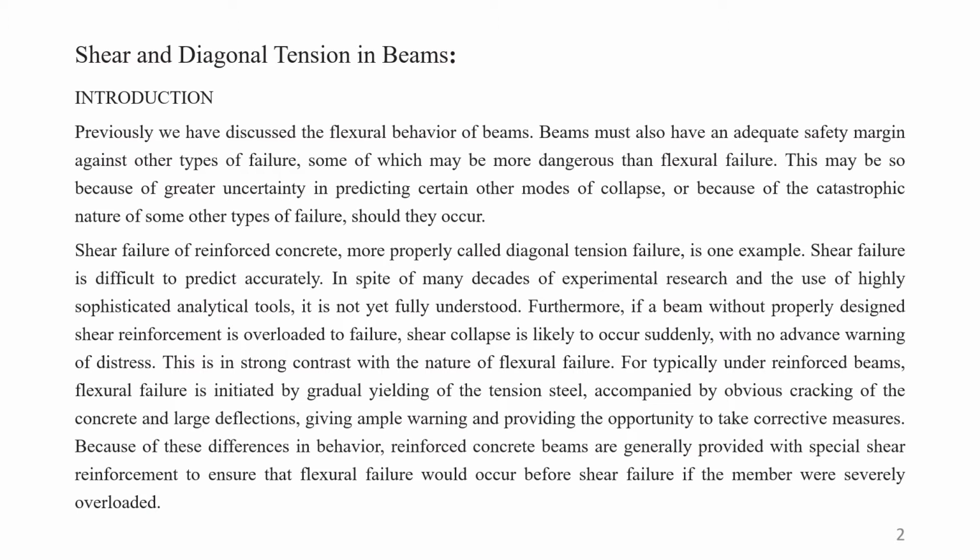Here we have shear stress or shear force. Some part of this shear force will be taken care of by the concrete section, and some part of the shear value will be taken care of by steel. Because if we do not use steel, the shear failure will be a sudden failure, which we never want. Therefore we will be using concrete and steel, and the steel will take some part of shear.